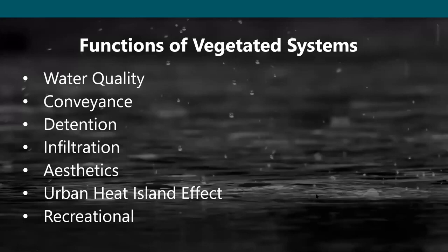And then when it comes to surface detention, especially in Texas, where we do a lot of our projects, a lot of your site ends up getting allocated to a surface pond or a detention pond, and that can kind of eat up some of your real estate. And so what we found is that you can actually kind of maximize your lot yield by incorporating some of these vegetated systems like bioswales and bioretention.